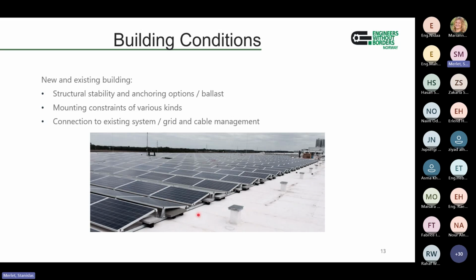I don't know if you see my pointer, and if you remember the junction diodes, the diodes in the module. The modules are usually, it's less true now with the half cell modules and everything, but historically they were connected in 3 different series with a diode that can cut off part of the module when it's shaded.